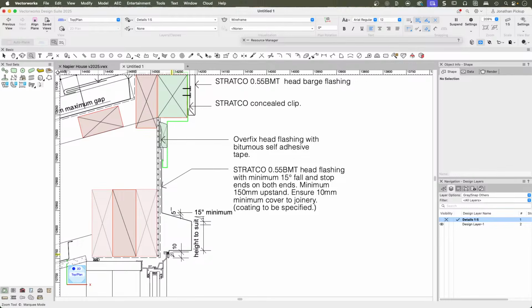It's just so hard. But making it in two stages also allows this height here and this one here to be different as the building goes along the edge. What if this is an angled roof? It's on a slight angle. You really want to be able to make sure that you can control that easily. A two-stage flashing allows one flashing to slide up behind the other, and you can get that to work really well. So don't be afraid to use that.